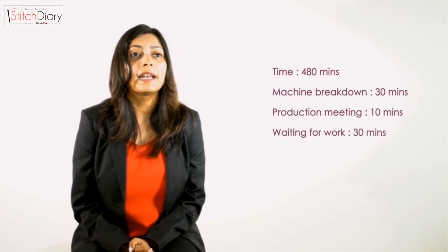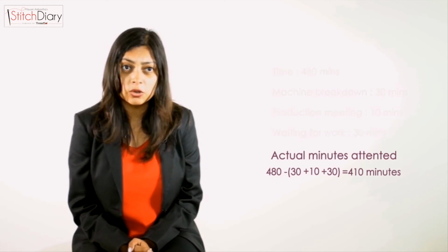So let's say an operator works 8 hours a day, so 480 minutes during the day, and during this time there were 30 minutes of machine breakdown, 10 minutes of production meeting and 30 minutes of waiting for work. So he spent 70 minutes on non-productive time or lost time. So the time that was available to the operator for actually performing the work was 410 minutes. During this time, he produced 22 bundles of 10 pieces each.